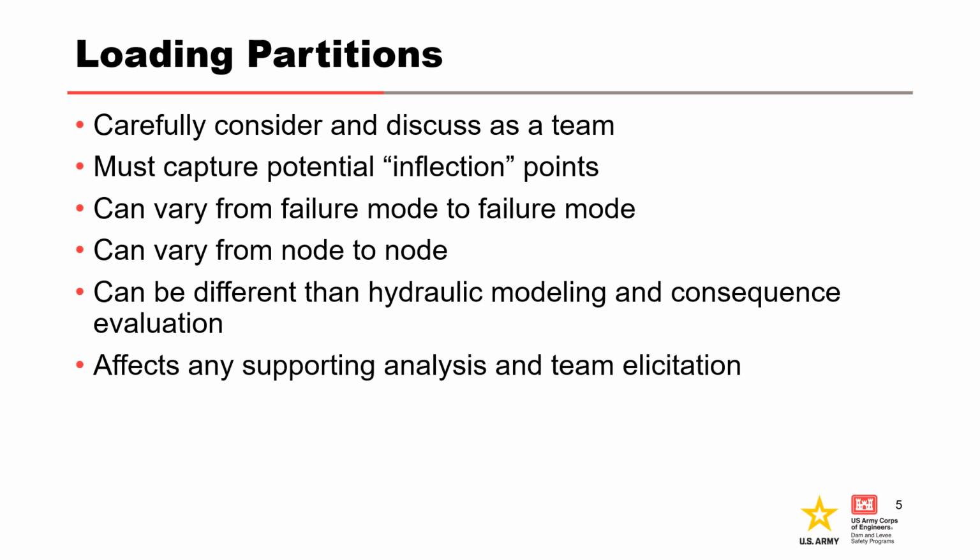Flood and earthquake loading partitions must be carefully considered and discussed as a team. The partitions must capture where changes in performance are expected, in other words, inflection points in the system response curve. It is important to note that partitions can vary from failure mode to failure mode, and even from node to node for a given failure mode.